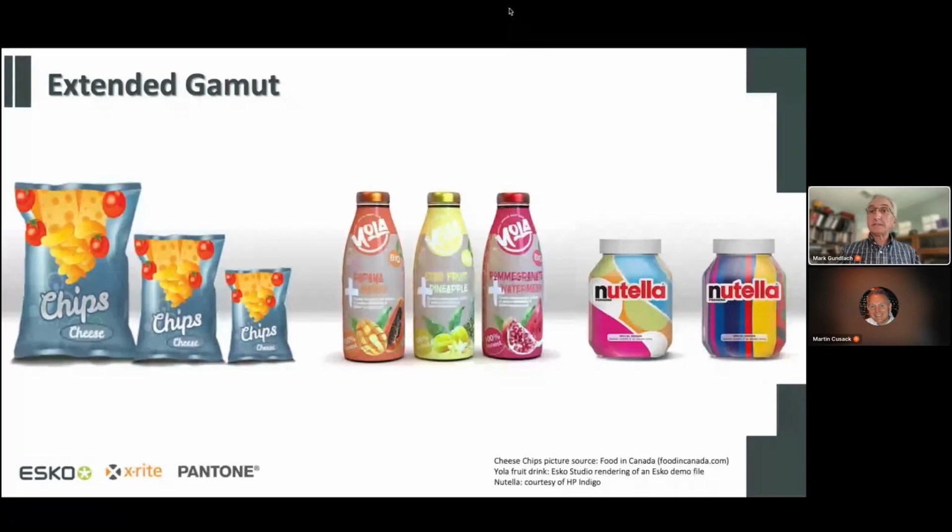Absolutely. And I would like to emphasize a little more about the standards. Currently the ISO standards are around the CMYK process. In extending that to the extended gamut, we're still going to calibrate and manage the CMYK part of this gamut the same way. And when we add the additional colors, the orange, green, violet, or red, green, blue, whatever, you will still calibrate those in a linear fashion. And then the data from that calibration and the data from that fingerprint are used by Equinox to do the conversions and optimize those colors to match on whatever substrate and press condition you're working with. But without having that fundamental calibration in place, you can't do all those things. So you do have to make sure you've got the calibration in place and you're set up to measure and maintain those targets throughout the press run.